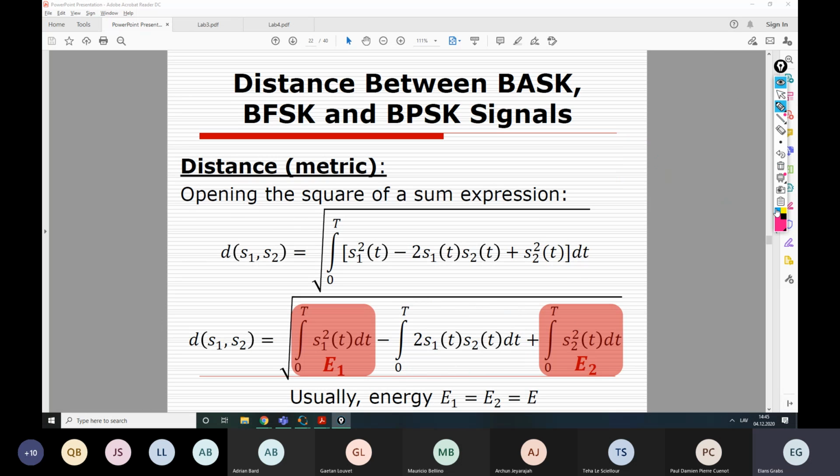Now, of course, there can be signals which do not have this shared energy, like these. These signals are called orthogonal, and that's why we want to use them for frequency shift keying, because they don't have any energy shared, and it's easier to separate them one from another. Also, let us note that usually, but not always, we use the same energy for both of these two signals.